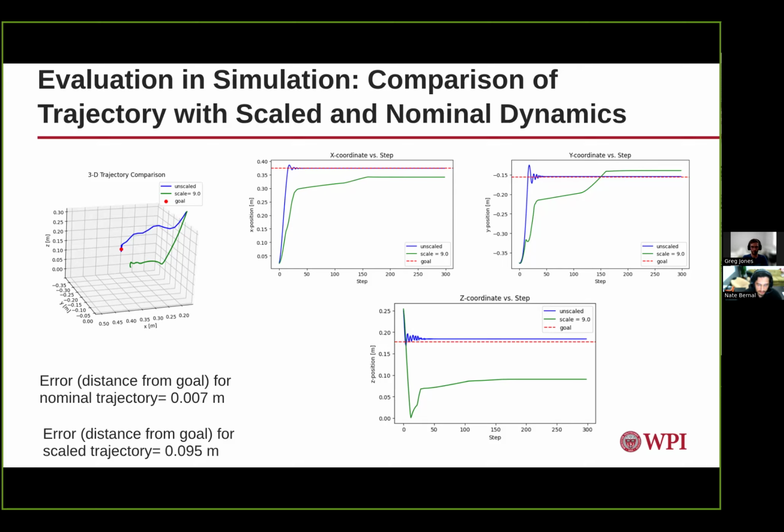The root cause follows directly from the robot dynamics. Each joint configuration receives roughly the same desired position command and the same effective torque. Scaling every link linearly inflates the mass matrix and gravity vector. Larger inertia terms reduce joint acceleration, while the heavier gravity terms can eventually demand more torque than the motors can supply, slowing progress and in extreme cases, preventing the goal from being reached. Next slide.